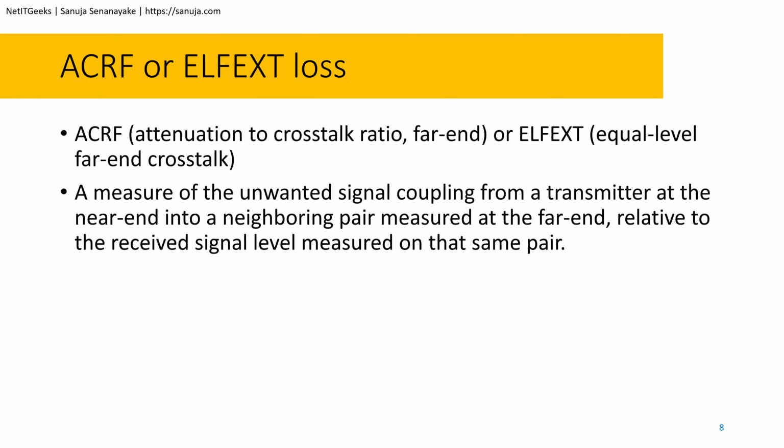It is interesting to note that digital signal processing, also known as DSP technology, can perform crosstalk cancellation, allowing some applications to expand usable bandwidth up to and beyond the point at which calculated ACR equals 0. So certain equipment may be operating beyond that.